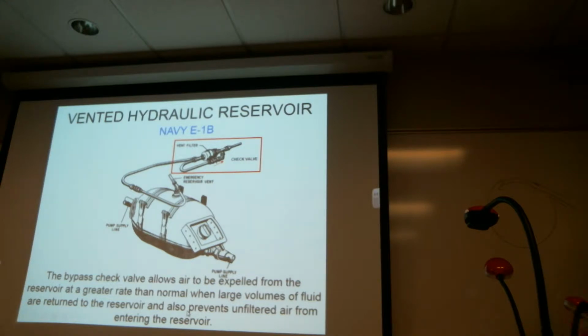So it prevents collapse of the reservoir if fluid leaves, and the vent also allows air pressure to get into the reservoir to push on the fluid. But you'll notice that they've installed a special type of check valve in parallel with the filter element. There's a reason why they did that.